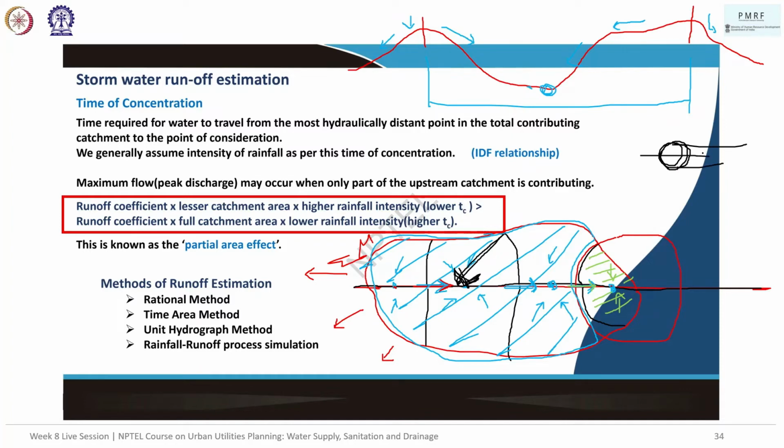So the amount of water movement in the pipe, if it keeps flowing, then say you're designing it for how much ever water is going to come in 10 minutes in this area, and say water is going to take 20 minutes to reach this point, which means by the time this 10 minutes of water flows in here, this pipeline, whatever that particular section of water, is going to move ahead, right? So it so happens that the pipeline can take much more because of the gradual slope. I hope I'm clear, right?